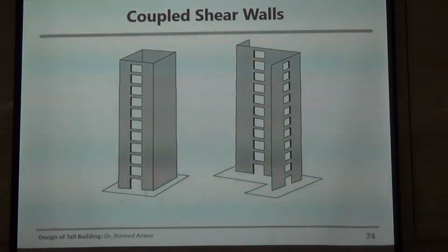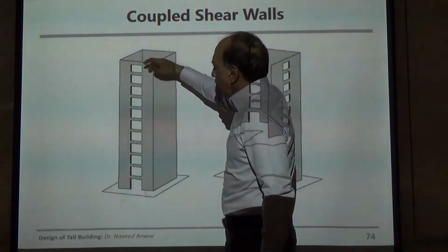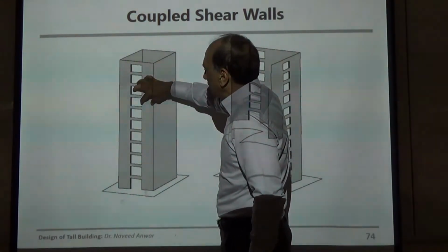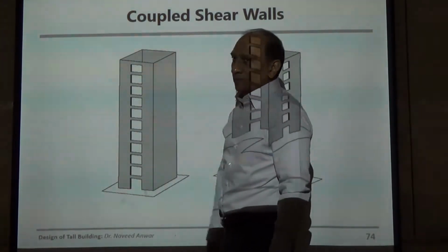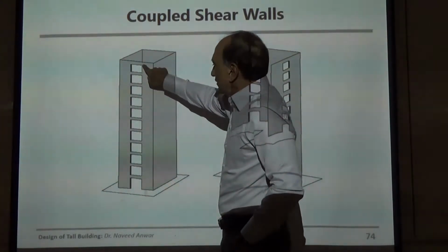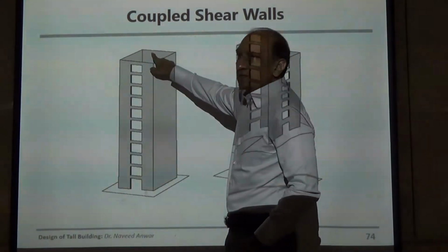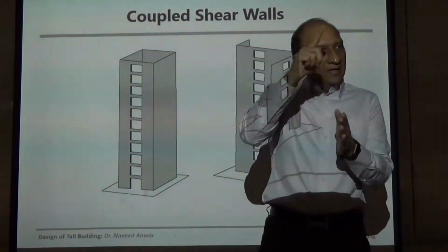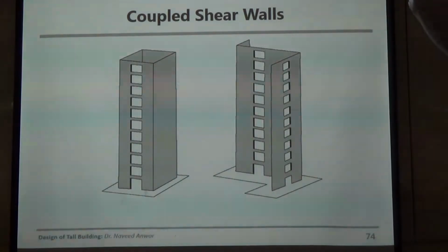So now these two walls, how much strength can they provide? Can they provide the strength and stiffness equal to the wall behind, or are they going to provide stiffness equal to these two separately? You know that this stiffness will be like 1/10 of that stiffness, because each wall is separate, and stiffness is equal to bd cubed by 12. So that depth is very large, this is very small, so it will be very small.